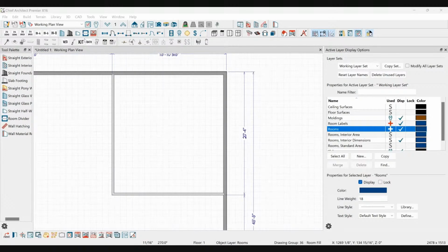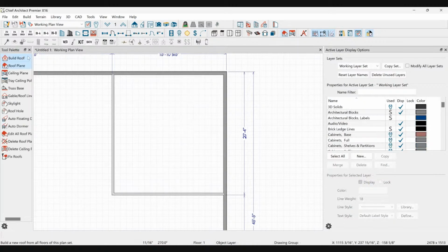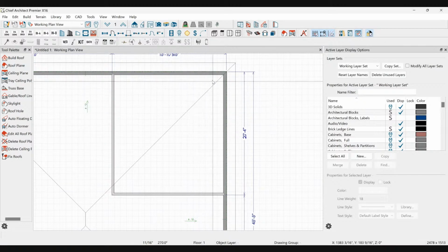The roof is a 9-foot plate, so my walls go to 9 feet. Let's build the roof. Let's say we're going to use a 6/12, which is very common. I actually want to auto rebuild all the roof. So if I build the roof like this, and it's a 6/12, and then I go look at the framing,